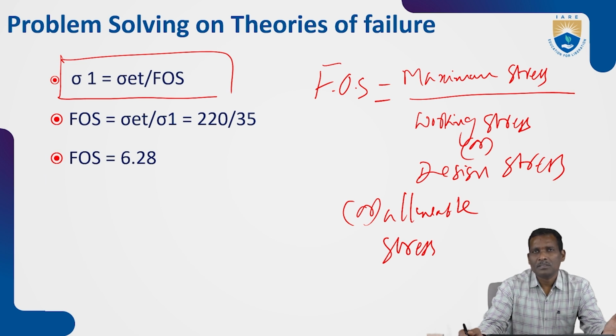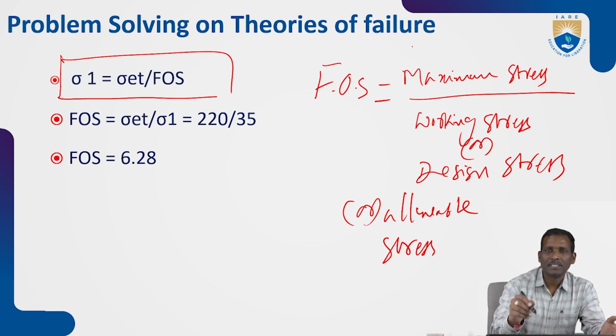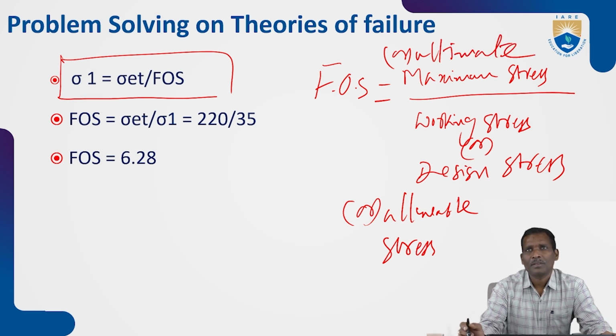So this is the factor of safety. So maximum stress, that is how much it can withstand, that is ultimate stress, upon the actual working condition stress, or working load, or working stress, design stress or allowable stress.